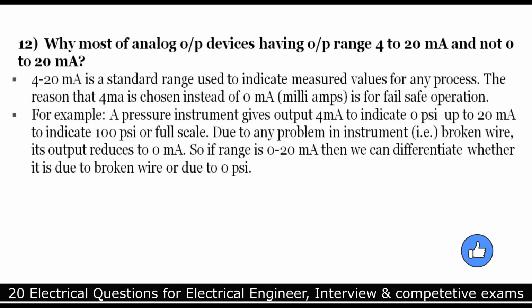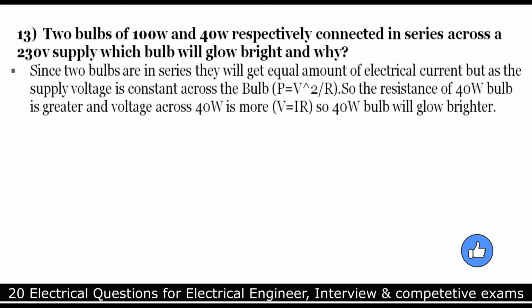So if the range is 0 to 20 milliamps, then we cannot differentiate whether it is due to a broken wire or due to 0 psi. Number 13.